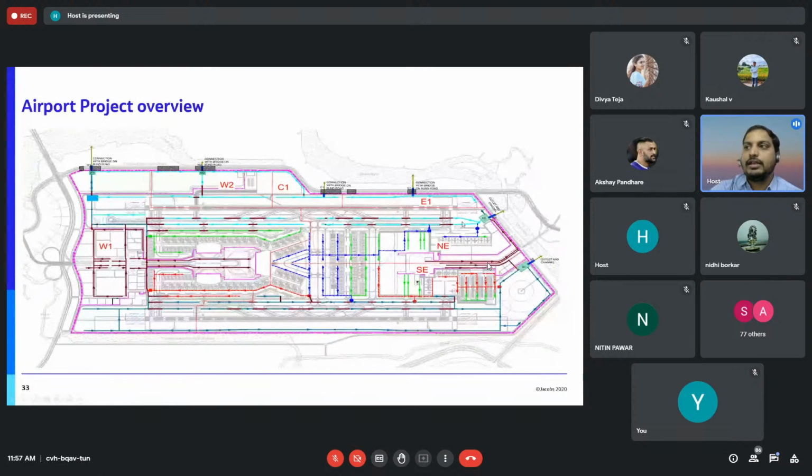When we are considering the other outfalls like W2, C1, E2, NE, all the systems will have a pond first. We are regulating our flow, then we are discharging into the natural stream. These are the common practices we adopt in Indian conditions. There are a lot of things we can talk about for every region. The stormwater part is very big when we are considering the design with respect to the smaller catchment and also the bigger catchment.